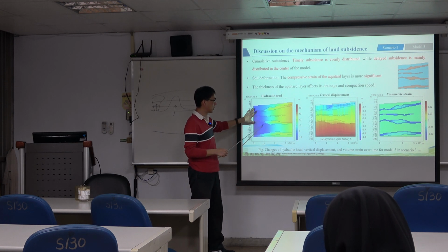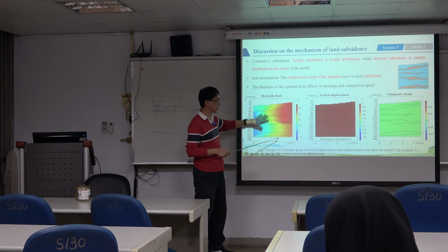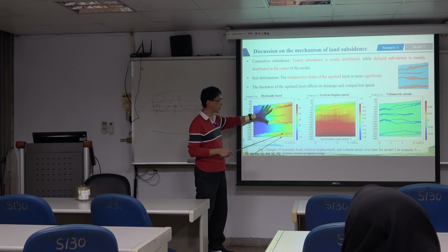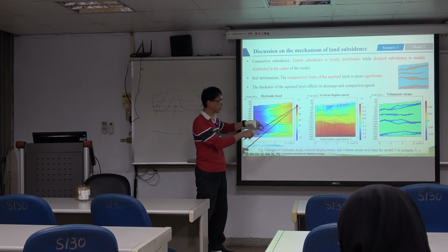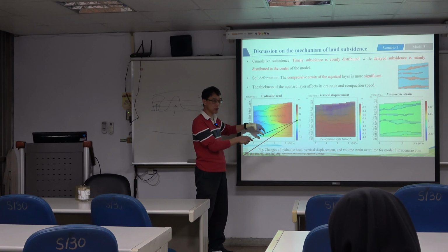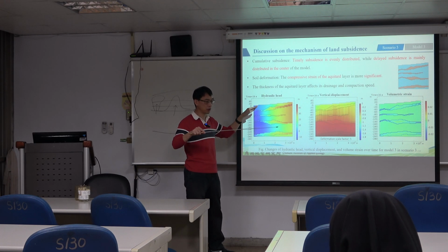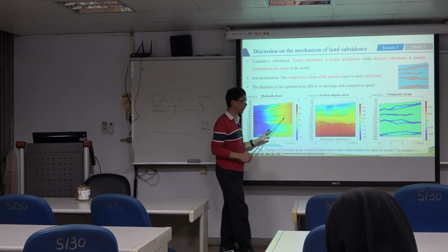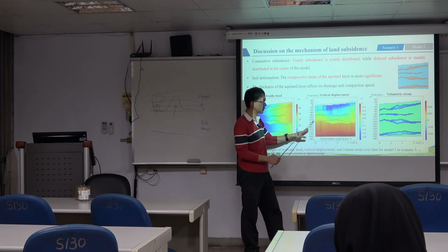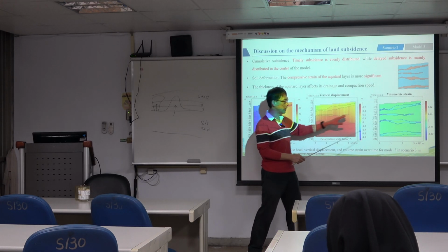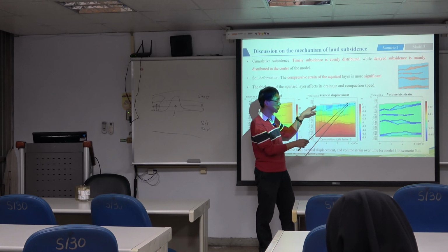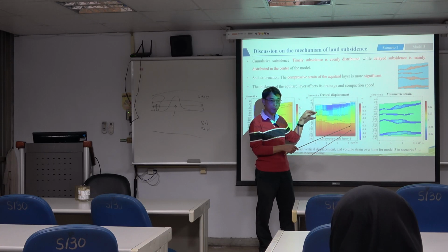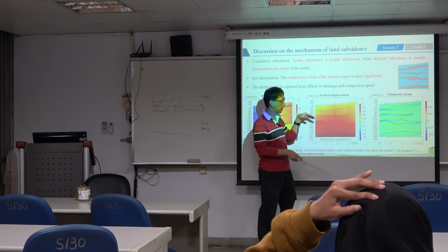And for the groundwater levels, we can see not a large difference, although we have the decrease, because originally it's relatively high, and then we decreased 15 meters and let it persist for a long period of time. Okay, so this is the groundwater level decline. And this is subsidence. Subsidence means that we are only considering the surface displacement, okay? The others accumulate together.